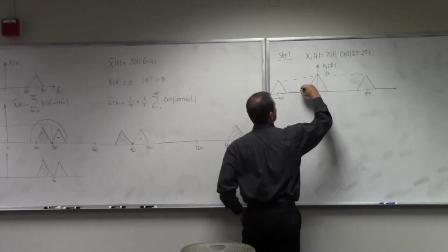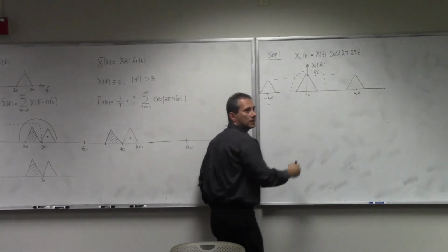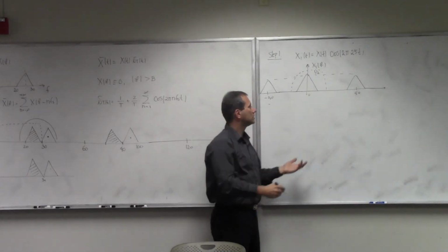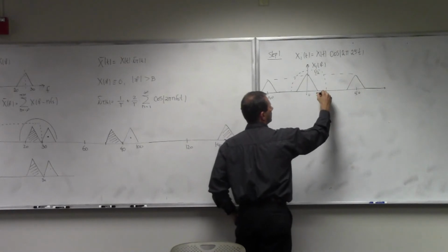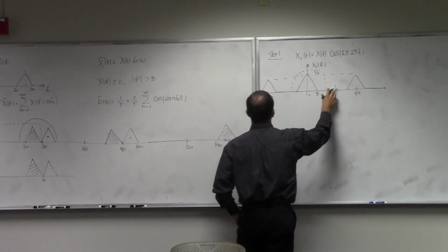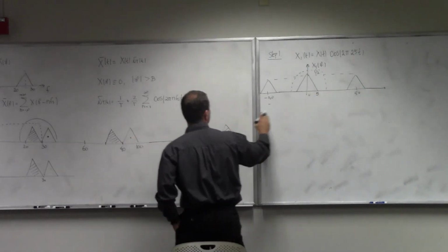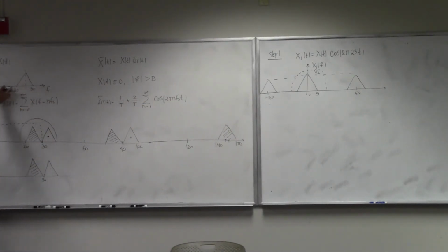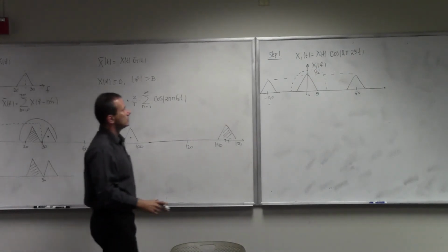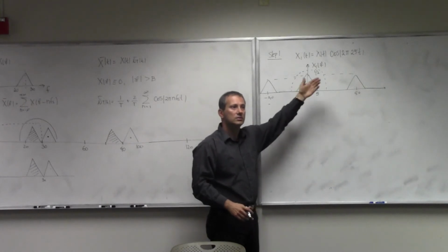Then the next step would be to low pass, right? And I get x2 of t to be just this. And then I can sample x2 of t. What is the sampling frequency of x2 of t? Should be 10, or twice that. The bandwidth here is 10, or 20. So when you bring it down, it ends up being 5, right? So now you can take this signal and sample that at 10, and then send it to the other end.